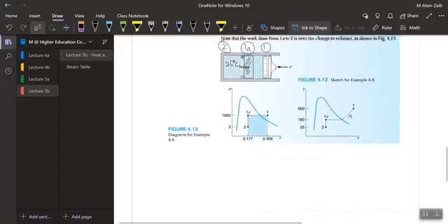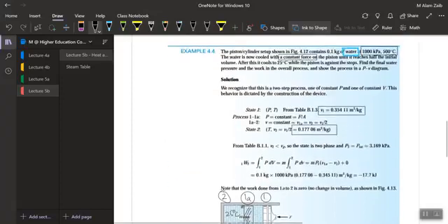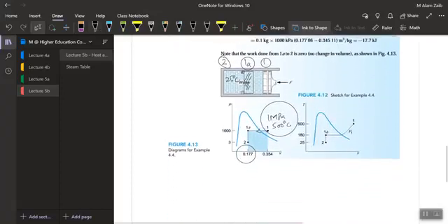So now if I write this on a PV diagram, initially at 1 megapascal and 500 degrees centigrade, I was somewhere in a superheated condition. Then it was cooling, and in cooling the volume would reduce while keeping the pressure constant, reducing the volume to half of its initial condition. So we have got a volume of 0.17706, which lies inside the vapor dome. That means we are in a two-phase region, or a mixed region.